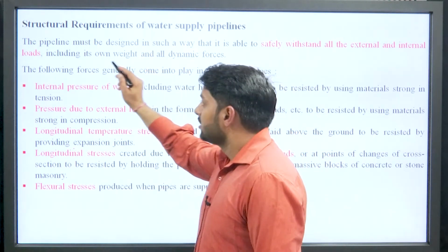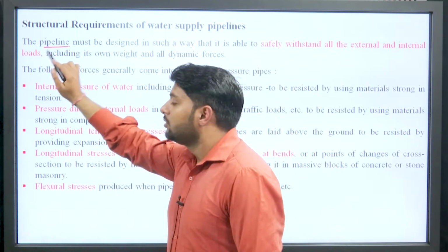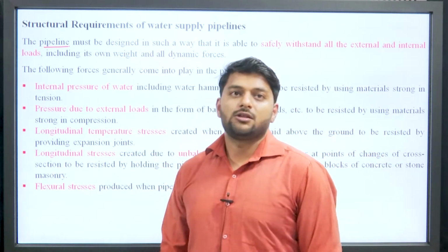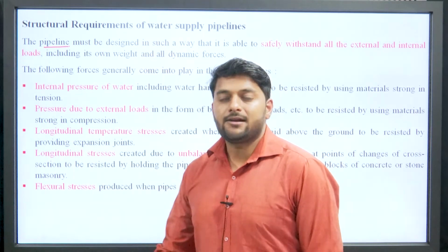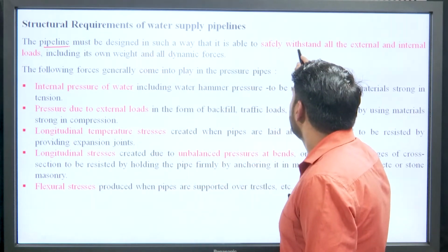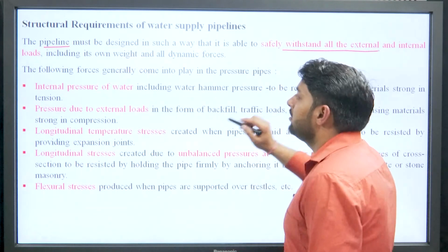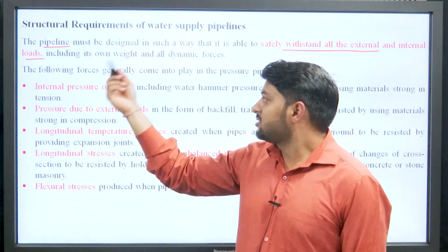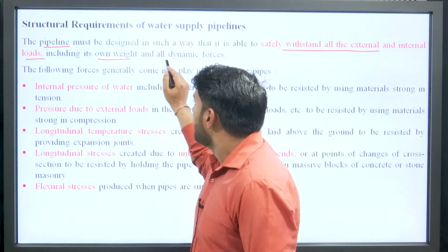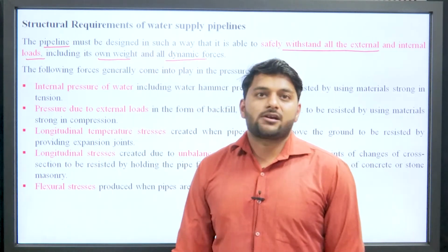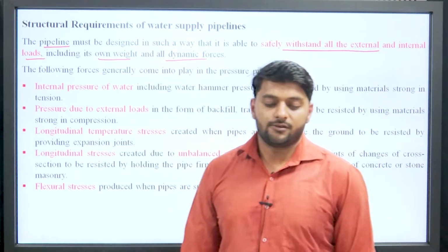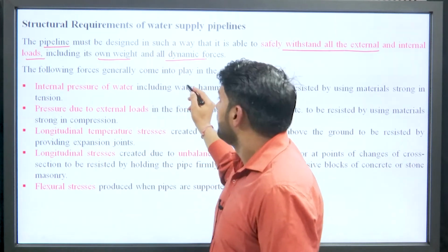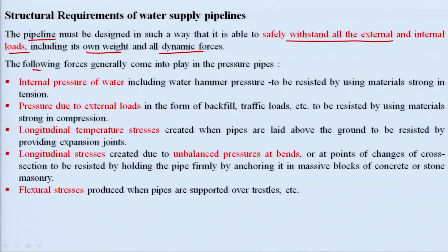So, what is the structural requirement of water supply pipelines? Basically, the pipeline which we are going to design for the purpose of water supply should be capable of withstanding all the external as well as internal loads, its own weight, and different dynamic forces acting on the pipe. When we group all the different forces, the following forces